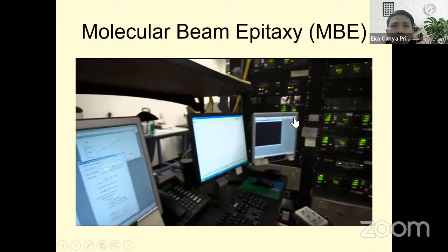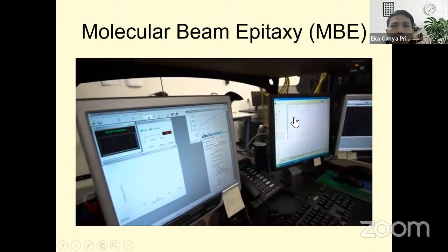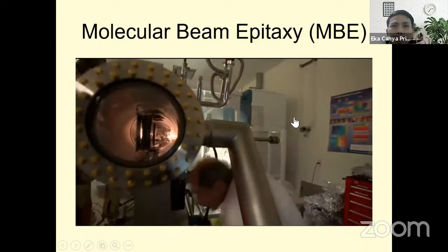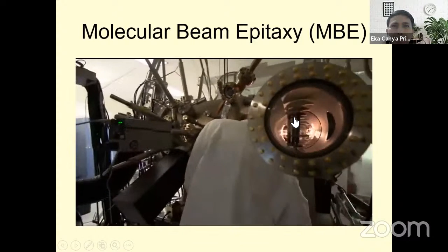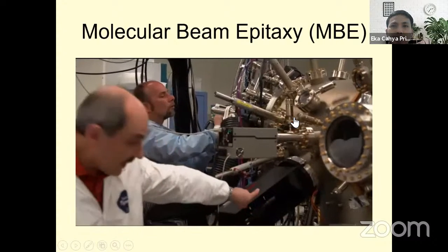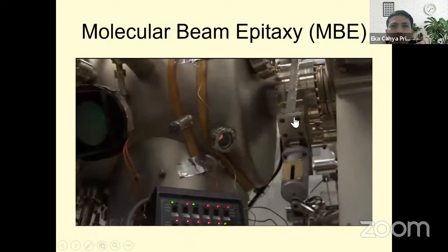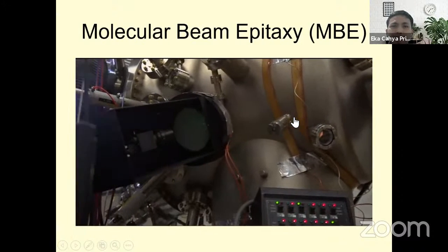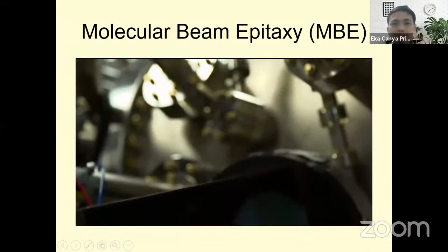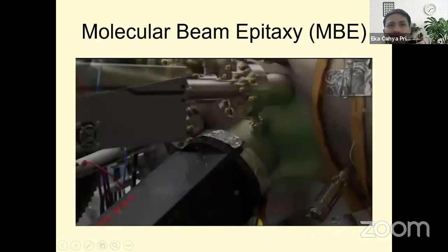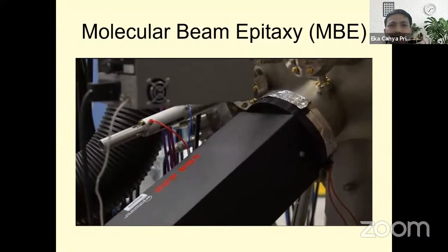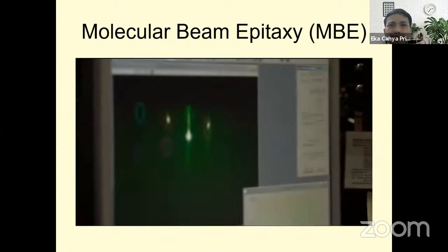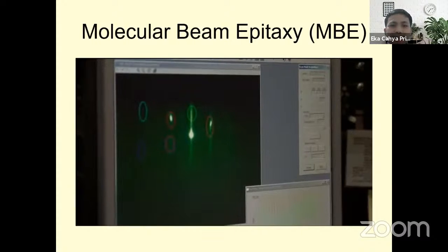Every morning, Bob comes in, and the first thing he does is he calibrates his source cells by looking at the KSA 400. I actually did try a competitor's instrument when I first set that machine up. To use a technical term, it sucked eggs. The KSA 400 in particular at the time was a really powerful tool at a good price for analyzing electron diffraction patterns in an MBE. And the 400 makes it extremely easy for him to get the data from the diffraction pattern, analyze it, and tell him what his growth rate is. I'm guessing it takes him probably 5-10 minutes at most.